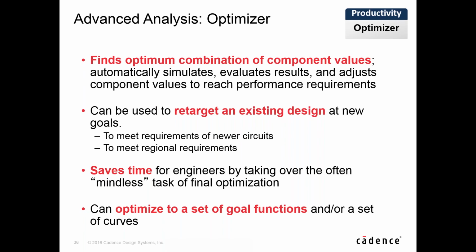You may have a layout already completed, right? And you now may have the option of just placing different values of resistors or discrete components into that circuit to redesign that circuit for an existing design, or maybe different regional requirements. That's another advantage of PSpice: the same schematic engine that drives PSpice drives your PCB layout. So you can use this optimization engine to keep the same layout and vary the components that are placed in that layout. And it saves a ton of time.